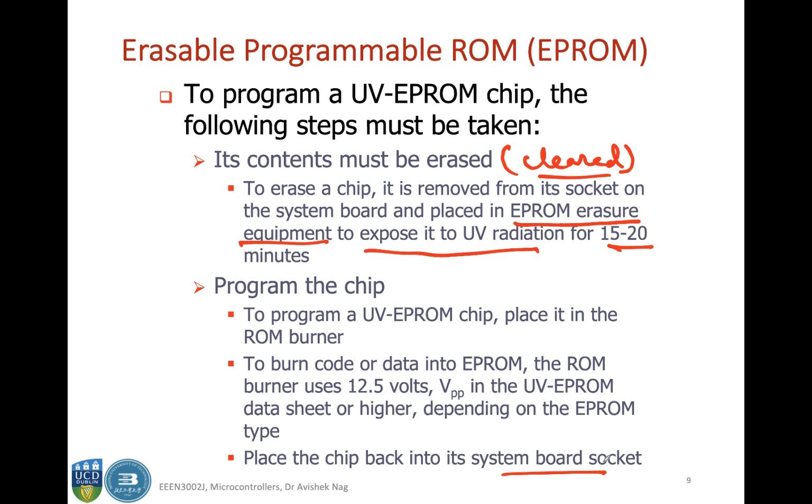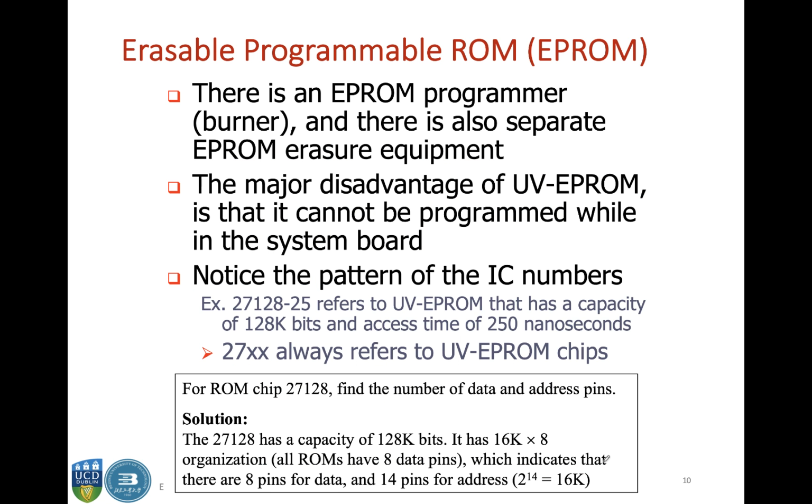Okay, so there is a separate programmer and a separate EPROM eraser equipment, and that's actually the major disadvantage of EPROM, that it cannot be programmed while in the system board. So it has to be moved back and forth from the system board to the eraser equipment, and then back to the burner, and then to the system board. So this is one disadvantage of EPROM.